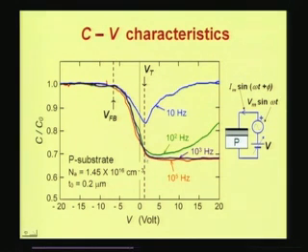Now what you note is that the threshold voltage is more easily noted from the low frequency curve than from the high frequency curve. This is because it is difficult to know where exactly it has stopped changing, okay, or where exactly it is saturating. Whereas in the low frequency curve you have a sharp change here which enables you to locate the threshold voltage.